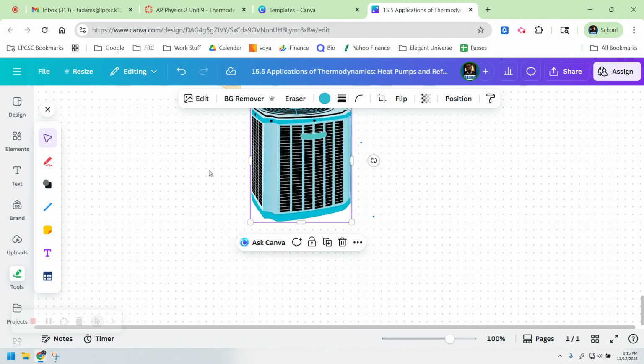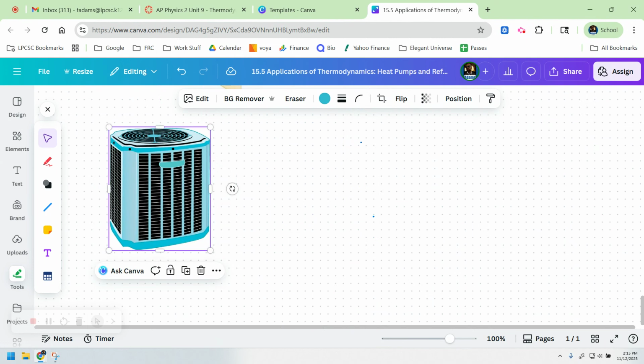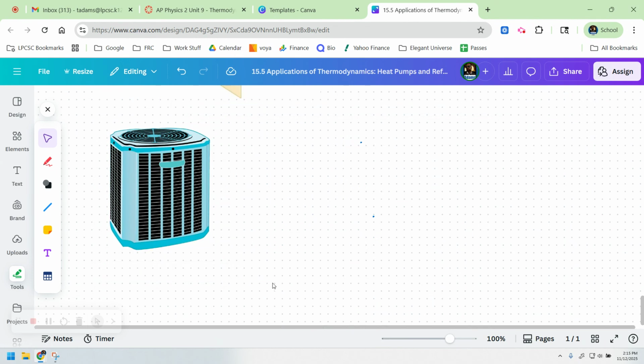So that was a heat pump, how you take, even though the air outside is cold, you create a cold reservoir that's colder than the air outside. The heat from the outside transfers into the colder reservoir. That heat gets transferred in with some work, and the work plus the heat heats the inside of the house.